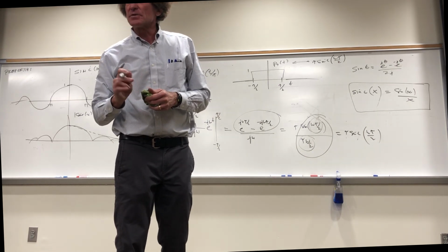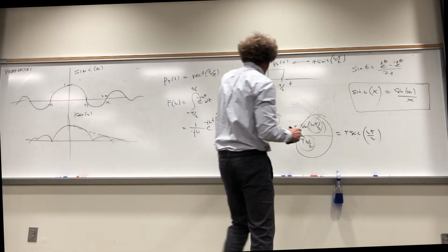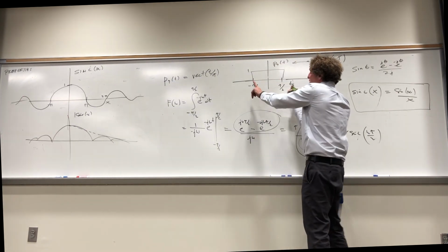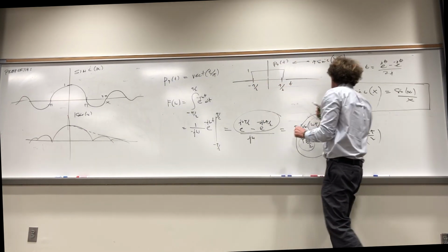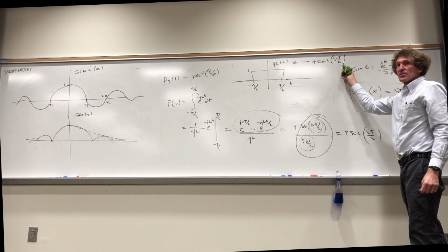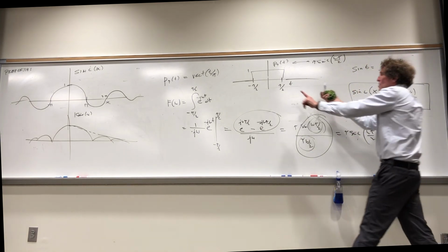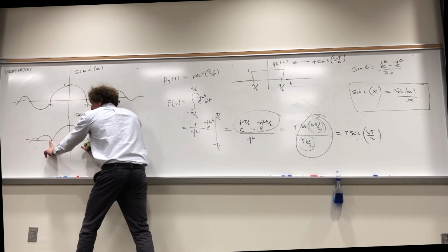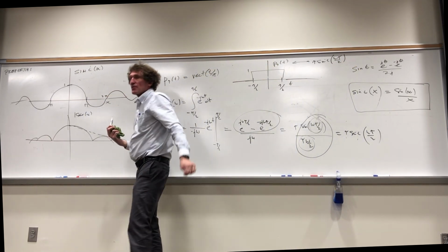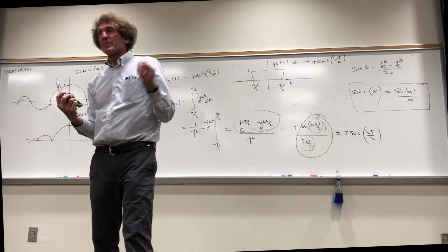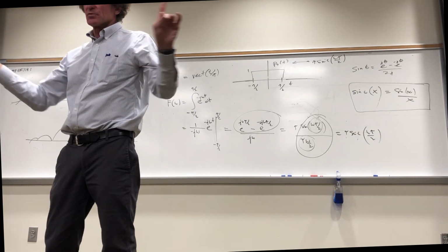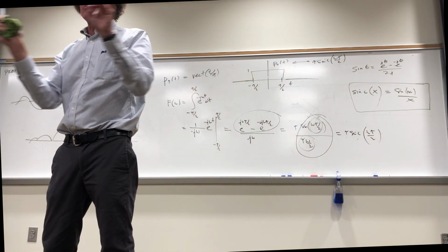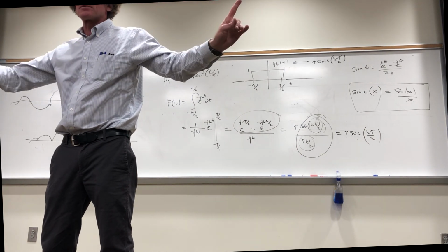Now, that is the transform of this function. And what do you see happening? The narrower this gets, right? If you look at this function, you have omega tau over 2. The narrower this waveform gets here, the broader this first bulge, the main beam of that thing, gets wider and wider. Narrower in the time domain, wider spectrum in the frequency.